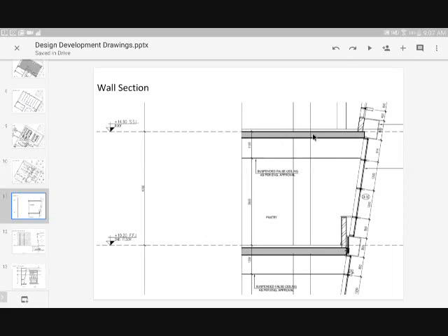This is the concrete slab and the flooring materials. We don't need to show all the layers. This will come later in more detailed drawings. But we show the concrete system and the thickness of the flooring. Is it 2, 4, 5, 6? What type of layers do you have to cover the concrete flooring? Any brickwork, and then the glass cladding of the building. So we need to show a section in one floor that we have here in the drawing.